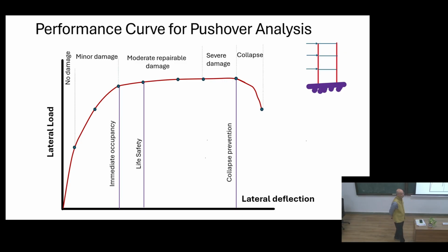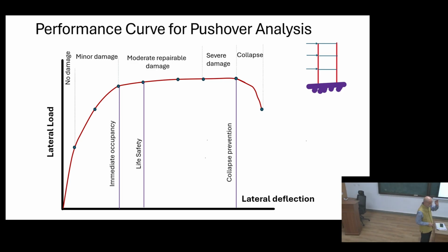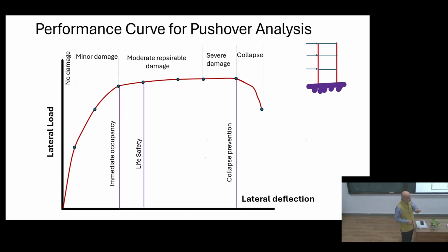So how has that curve come about? This is an illustration again, and I did this to get more clarity in understanding performance-based design. This is a force deformation curve. If the force deformation curve is understood well, performance design is a very easy task, or you can grasp it easily. What are your targets, what is the input, what is the output, declared.